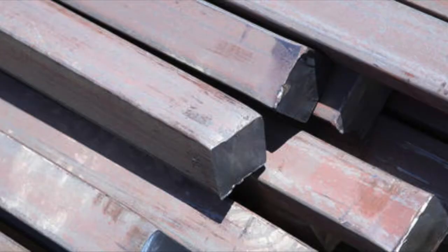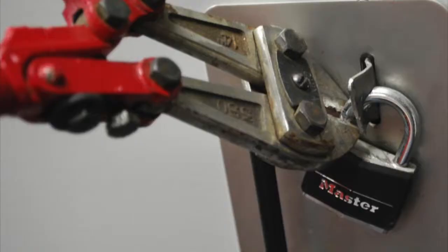In selecting a material to be used for the padlock shackle, the design specifications need to be considered. The shackle must be able to withstand large forces from prying, impact, and shear caused by bolt cutters. Because of this, most shackles are typically made of hardened carbon steel alloys. These materials are generally fairly cheap, allowing for shackles to be made at a fairly low price. If we allow the cost to be less of an inhibiting factor, we get a more diverse selection of materials to be considered.